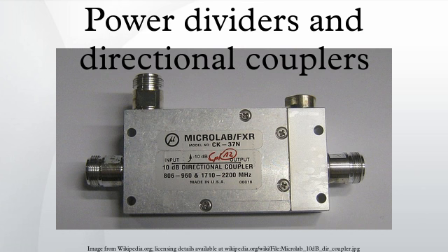A signal is coming in one line pair. One transformer reduces the voltage of the signal, the other reduces the current. Therefore, the impedance is matched. The same argument holds for every other direction of a signal through the coupler. The relative sign of the induced voltage and current determines the direction of the outgoing signal.